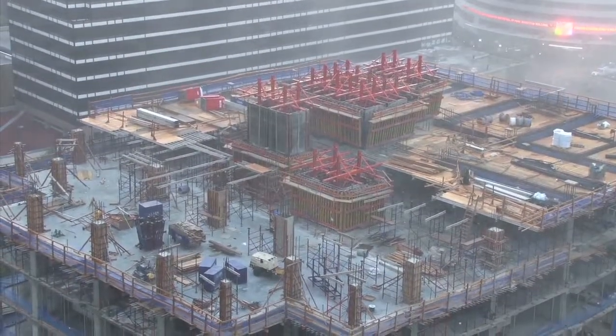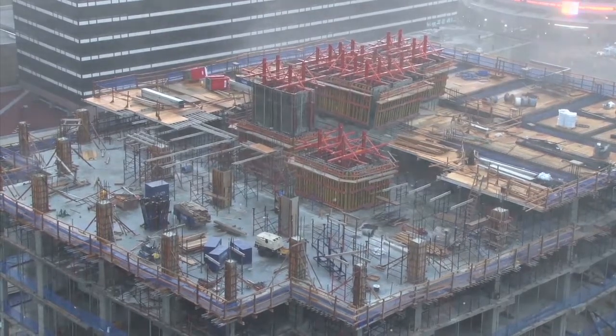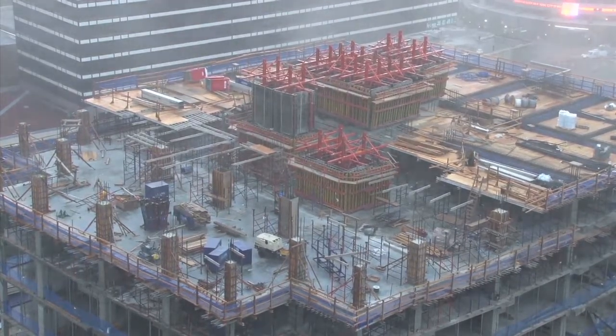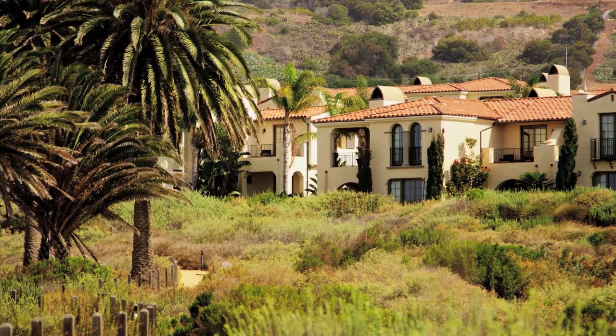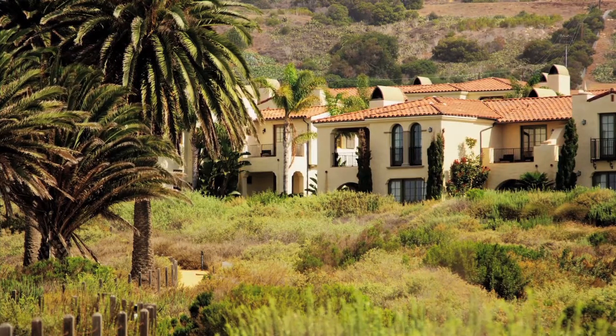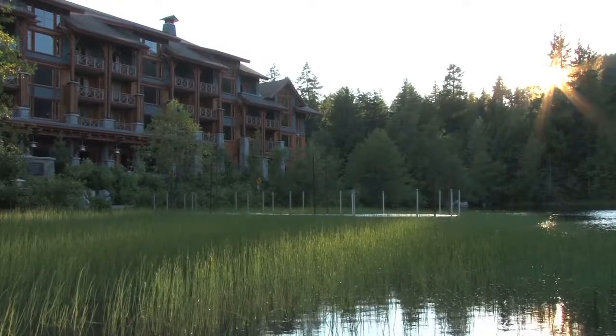For multi-tenant complex projects, the requirements may be met using a coordinated approach for multiple building projects. This could include a group of distributed low-impact development techniques within the boundary of the master plan to manage rainwater generated from the project site. If a coordinated approach is used for the multi-tenant or multiple building areas, distributed low-impact development techniques based on a watershed approach are required.